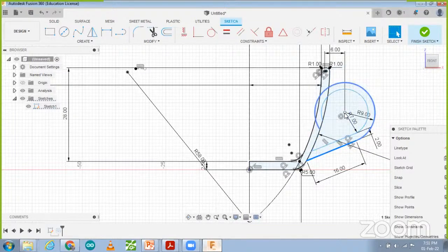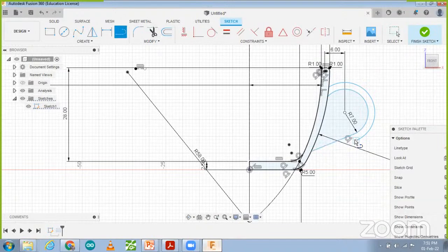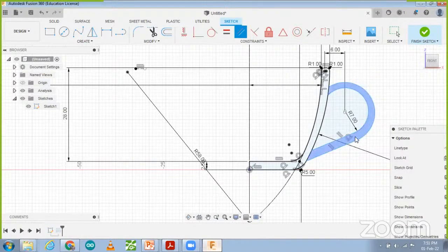So then what next we have to do, the distance is already given. So go to the edit part, cut part, and this one part I'm going to cut. That is not required. And this one we made it, yes, one line also got deleted. So let me make one more line again from this point to this one. So both we can make parallel. So automatically the dimension is being defined. This one dimension is already given, that is 16, so that we can take. So this.